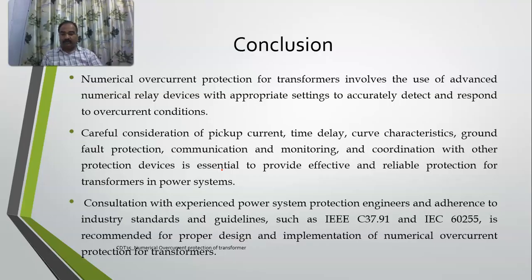Okay. So on the whole, I hope that now you have understood how these numerical overcurrent relays are implemented. It's all about, they use very advanced numerical relay devices. So what all you need is nothing but you should develop an algorithm. And if you are a good programmer, then automatically you can write that code. Okay. You must carefully consider the pickup current, time delay, curve characteristics, ground fault protection, communication monitoring, coordination with other protection devices. All these things you must be careful about. So based upon that, you will be developing the algorithm and then you will implement the code.